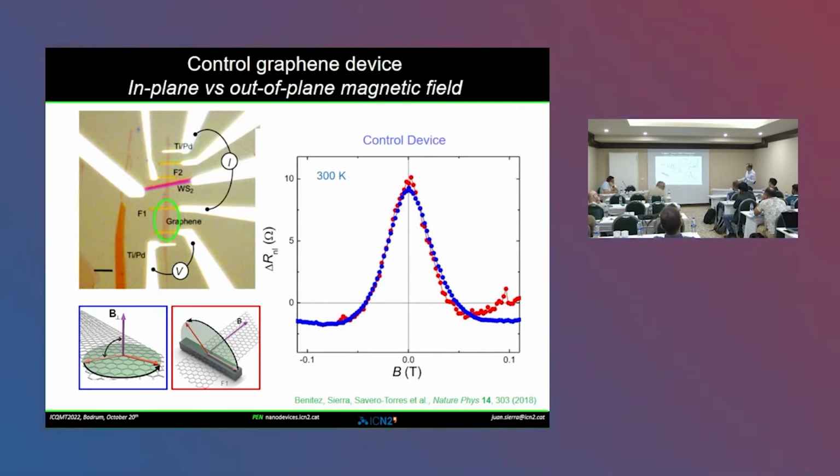And here you have the characteristics of graphene. So you see that the charge neutrality point is at this gate voltage around 15, and fortunately we were in the region in which the TMD is not conducting. So we were able to measure these effects to be sure that there is no current flowing through the TMD, and also we were able to distinguish how the system behaves if you have holes or electrons.